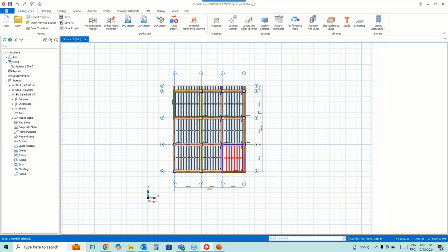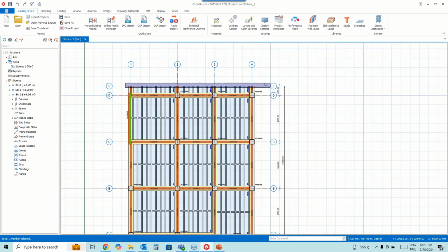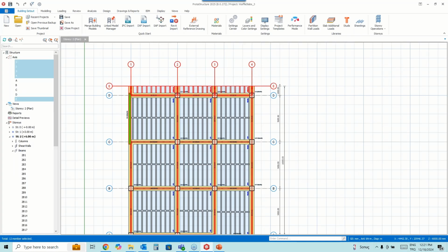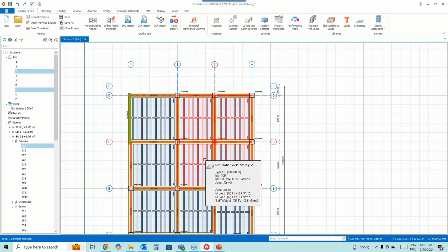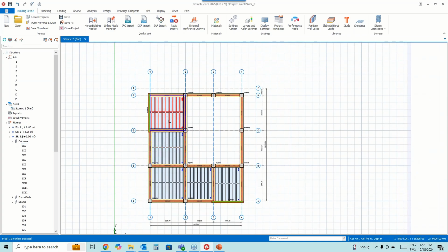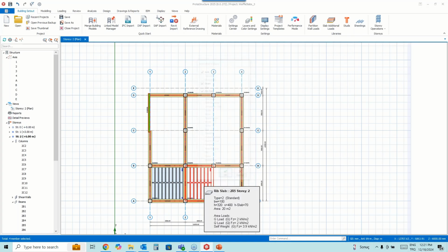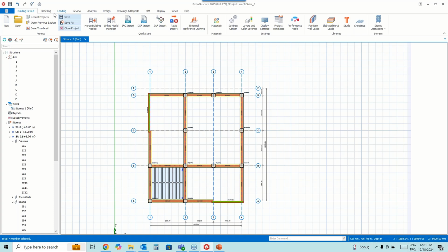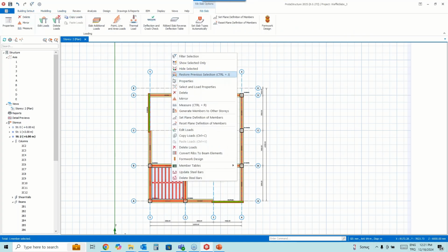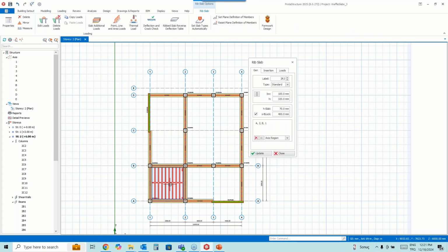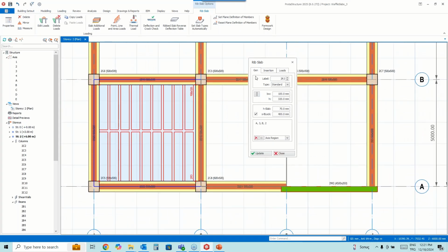Okay, so in this part, I'm gonna delete the cantilevers, and I will create larger spans like this. Okay, and this time we will use waffle slabs. So what I can do in here, I will transform this rib slab to the waffle slab by selecting the grillage option. Of course, I'm gonna slightly change the waffle slab properties.